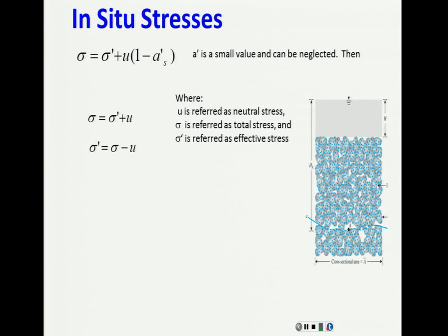Now, if you get that very same truss, you submerge it in water, and apply the same loads to that truss, guess what? Well, you shouldn't have to guess, you should know it. But anyway, guess what? The internal forces, tension and compression forces, axial forces in that truss are going to be exactly the same as if you compare them at the atmospheric pressure. That's, I would say, the closest analogy that we can get to this effective stress.